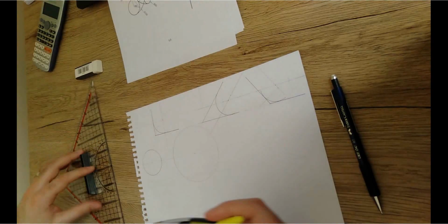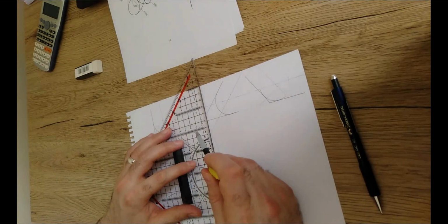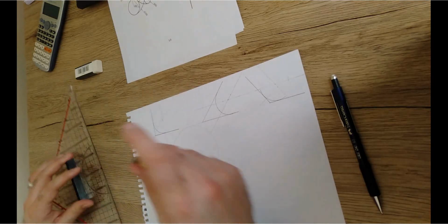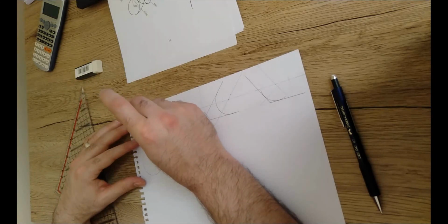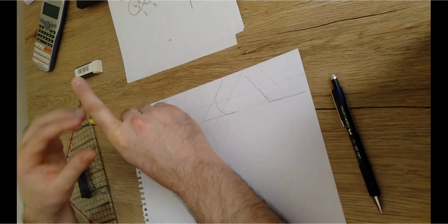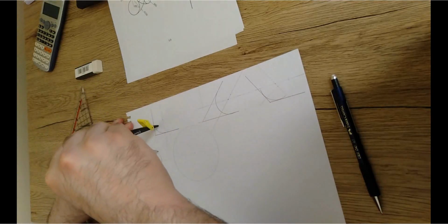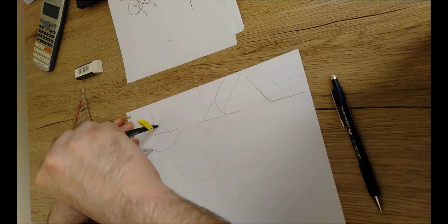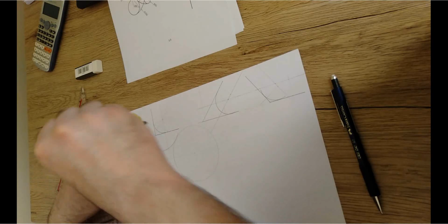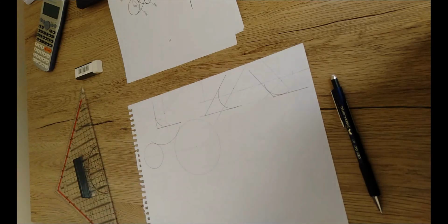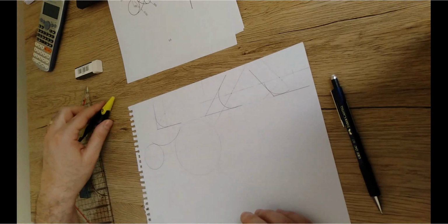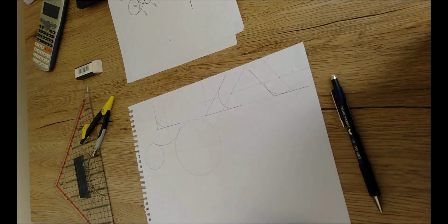So what does it mean? It means that I'm just gonna fix here. I'm gonna open with 40 millimeter. Then from this center point, I'm just gonna draw a line. This curve, if your measurements are accurate, it should be definitely tangent, as it is just acceptable for my case, right? We can repeat the same for the 300, as I'm gonna explain to you.